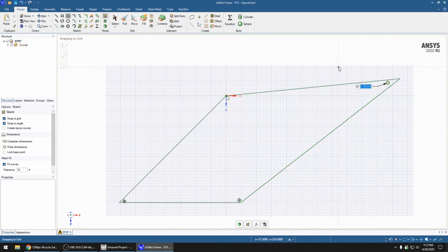Okay, and then in Ansys, we'll apply the loads down here, a fixed constraint here, and then forwards and down here. And then we'll put the front wheel in here and run it. And then Ansys will eat away at this frame material here, which it decides is not useful. And then we'll have a new bicycle frame.